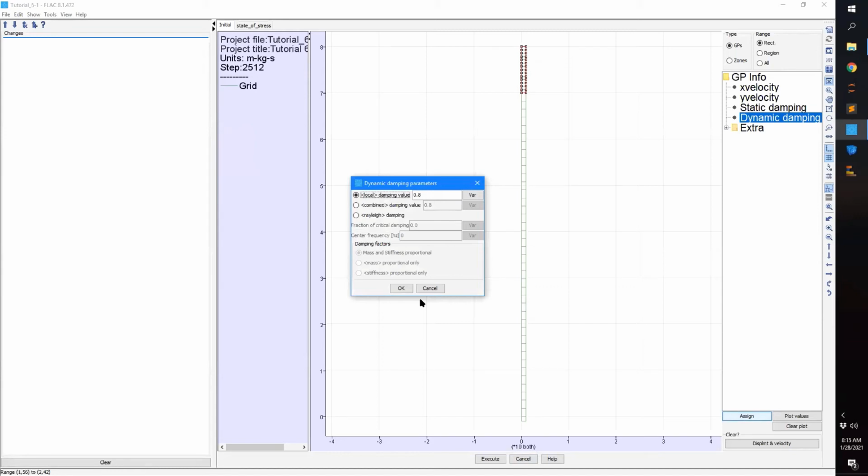That's certainly one option, but what we want to do is specify damping separately for the different materials. Here, I'm going to specify Rayleigh damping and the fraction of critical damping. This is the minimum value. I'm going to specify a value of 0.003. This will produce, on average, between about 0.5 and 20 hertz, a damping of around 0.5%.